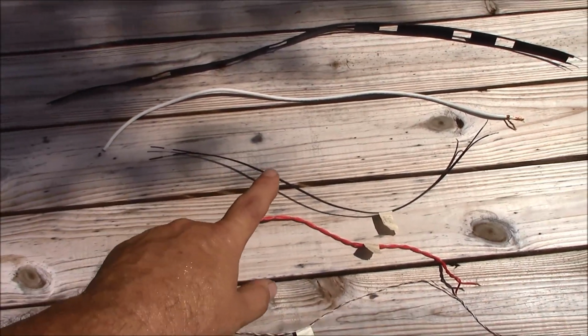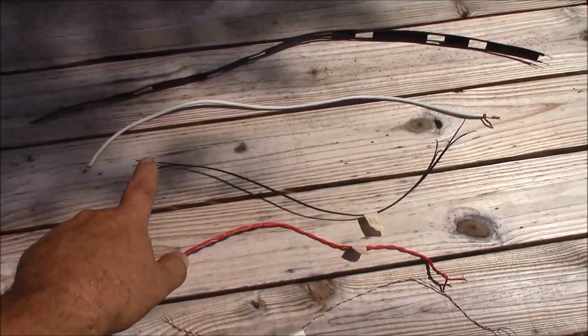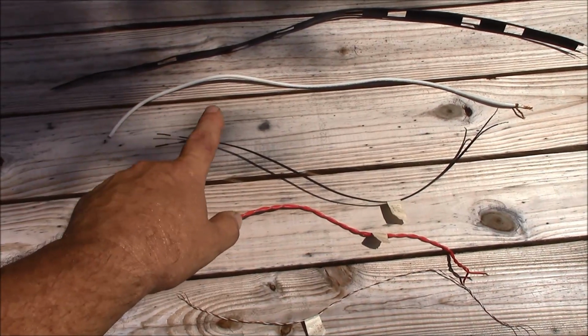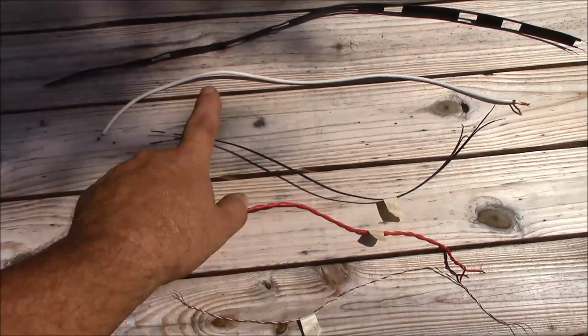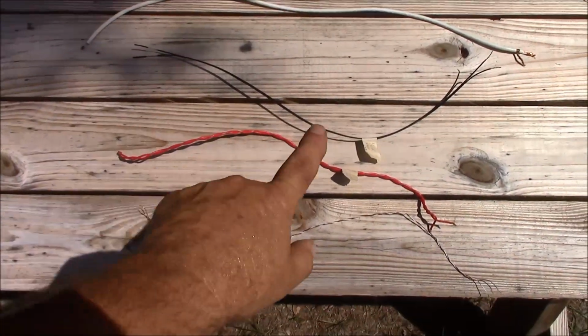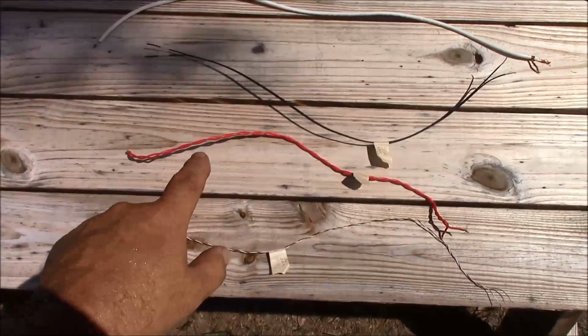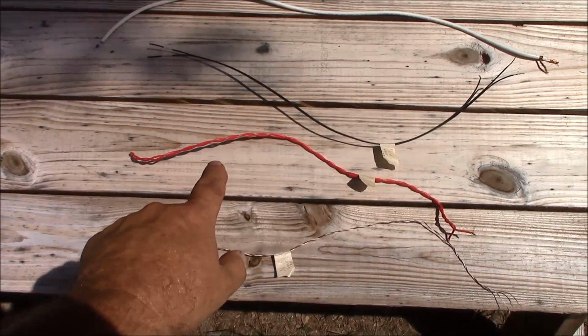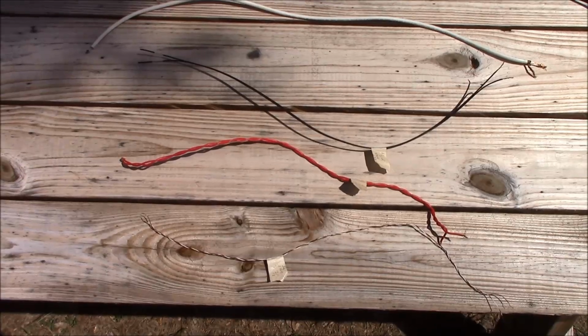Now with these smaller lines down here, the coaxial cable isn't that big of a deal. However, if we're making stubs and a balun out of coaxial cable, we're going to have to pay attention to its electrical wavelength. And when we look at our twisted pairs here, if we want to make it as efficient as possible, paying attention to the lengths you cut it to will assist you.